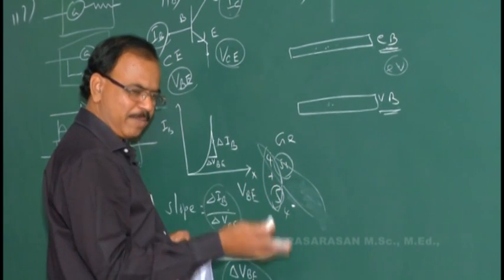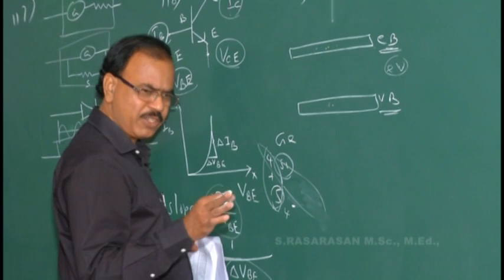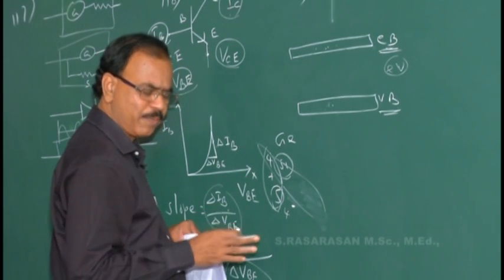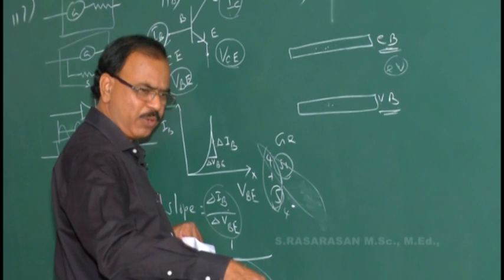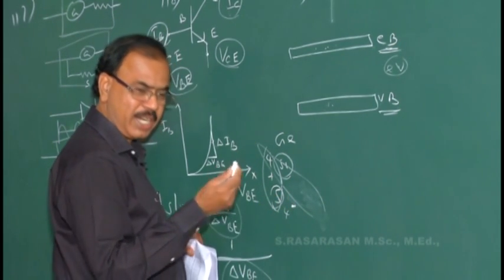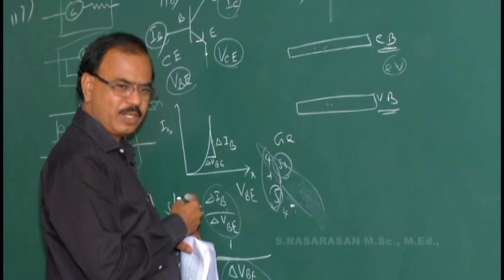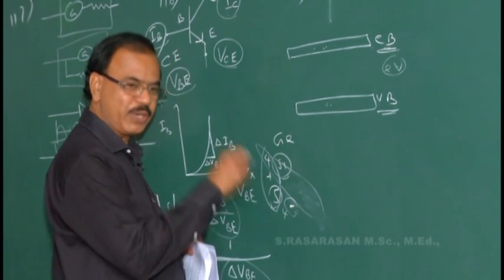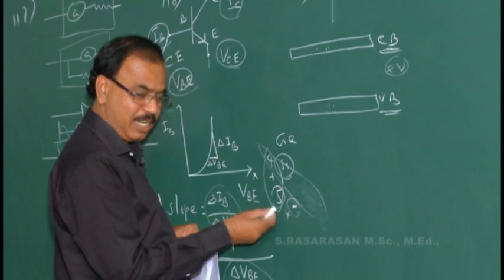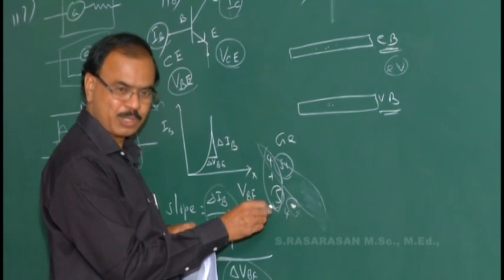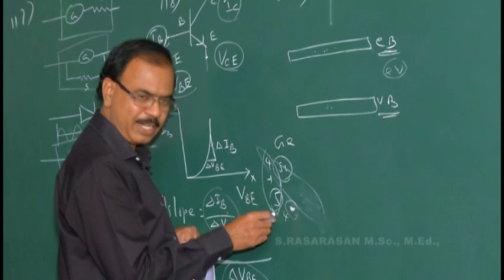In pure germanium or silicon, all electrons are held in the covalent bonds, not even a single electron is available for free movement. Conductivity does not arise, it is an insulator. In such silicon, if you dope the pentavalent impurity, 1 electron is moving here and there, and conductivity arises. If you dope 100 impurity atoms, 100 electrons are moving there. So we can increase the conductivity by doping impurities like phosphorus. So what brought conductivity into silicon that had none? This phosphorus pentavalent impurity atom, by donating the electron. That's why these pentavalent impurity atoms are called donor atoms.